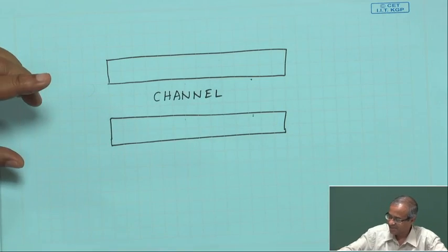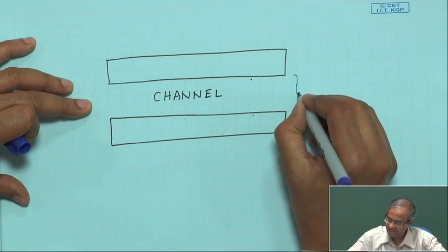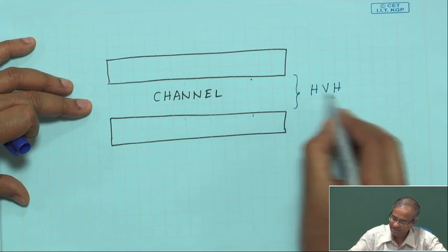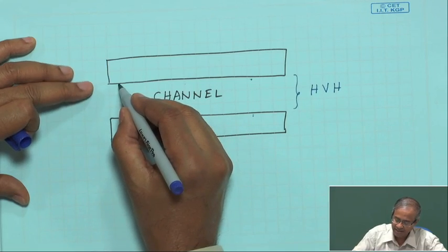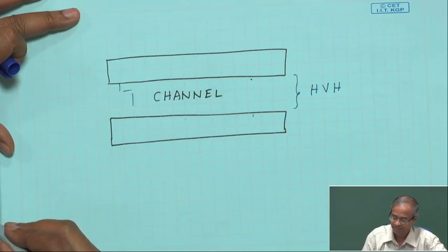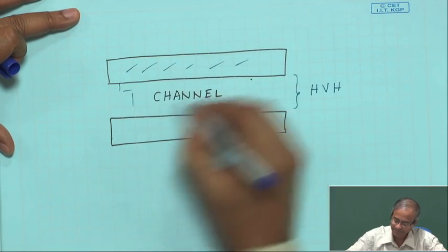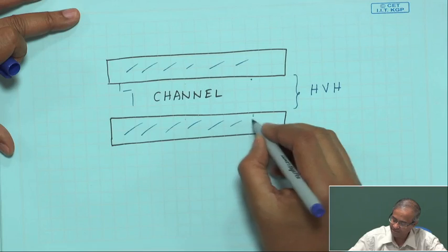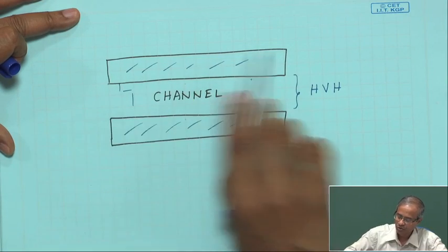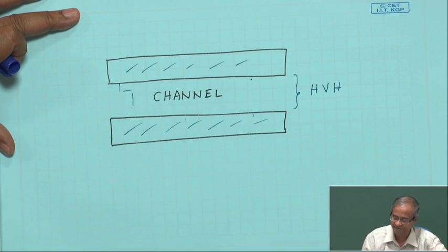Suppose in a 3-layer channel routing, using, let us say, the HVH model, there are 3 metal layers, and you are laying out wires on these 3 layers inside this channel only. But what about on top of these regions? Here the actual devices are fabricated, the transistors, the gates. On top of it, maybe one of the metal layers is available to you, that is free.